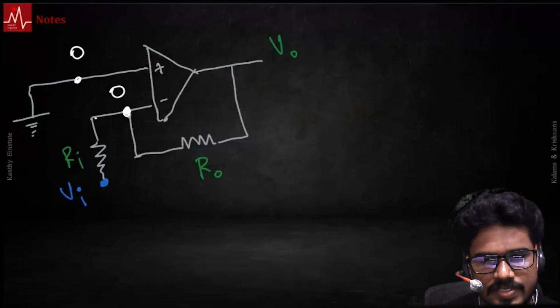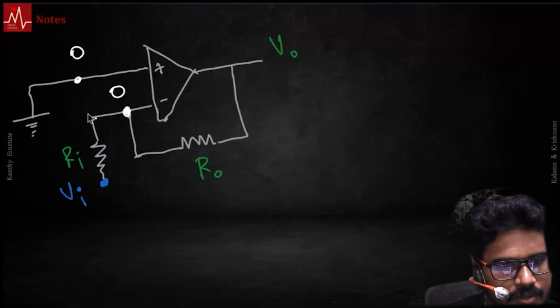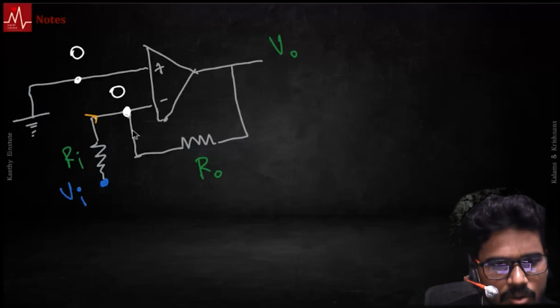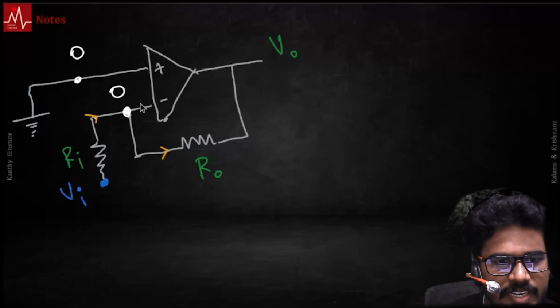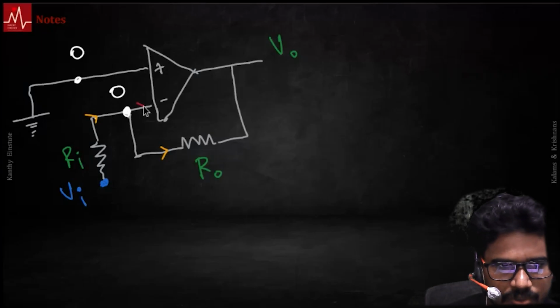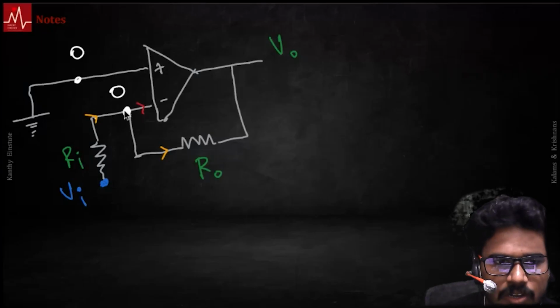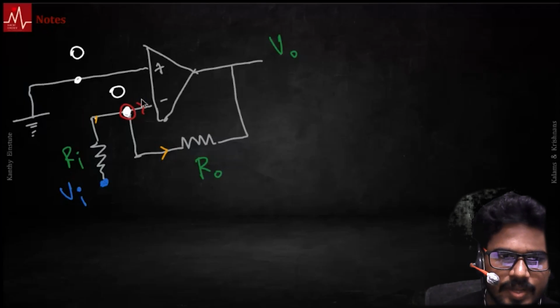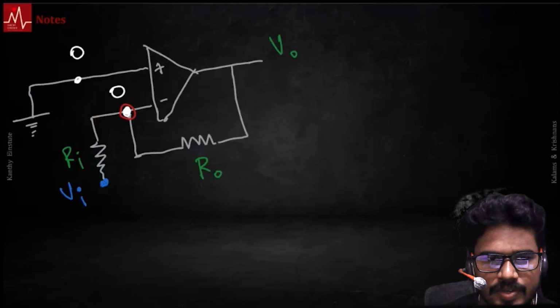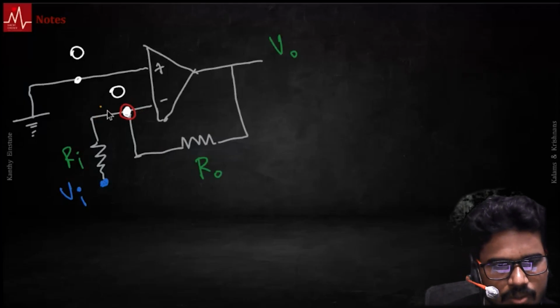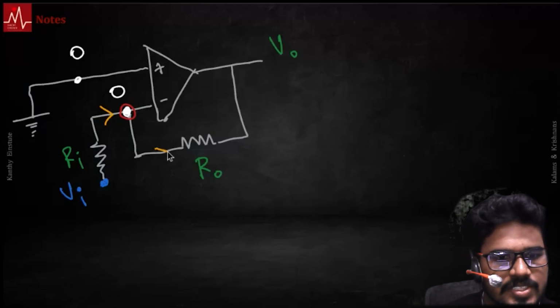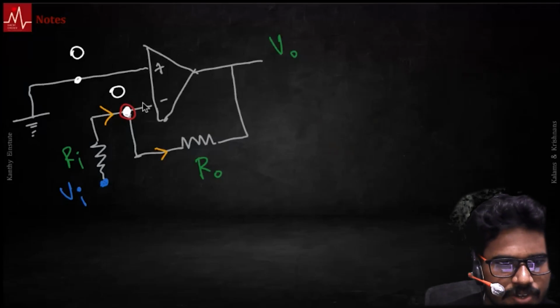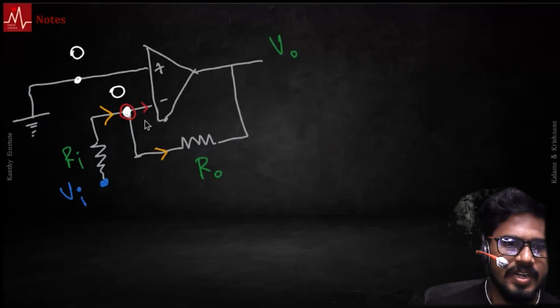And if there is any current, of that should flow here. None of it can enter this. So if you write current conservation at that particular node here, whatever shows in should all exit through this feedback loop. Okay. So current there is 0. So whatever shows here should all exit through here. None of it should enter here. That current has to be 0.